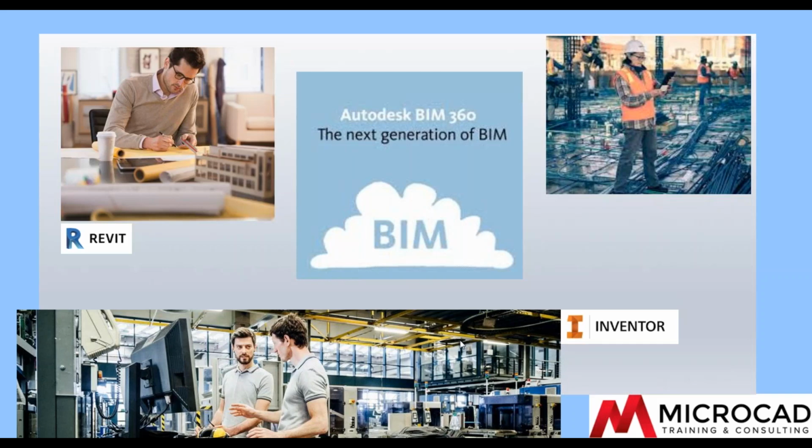The models become part of the BIM model, usable by everybody on the project. And because Inventor can link associatively with Revit models, the geometry created by the architect can be part of the Inventor model. And it updates automatically when the architect updates the Revit model. The intelligent model can contain additional data for asset control and facility management.